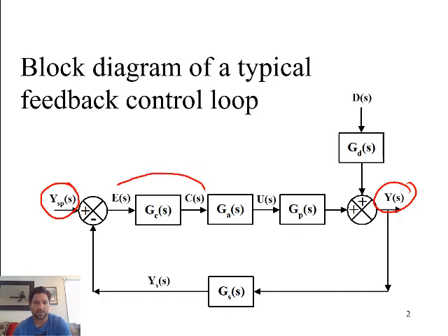What we need to look at first is the controller algorithm. The controller is going to take the error and determine how to change the input to the actuator in order to get our control variable at our set point. That's the objective. Essentially, we need to think about how the controller is going to work to get it there. It's going to change by a certain amount, and it's going to change at a certain rate. So how fast and how much is what the controller is going to tell the actuator what to do.